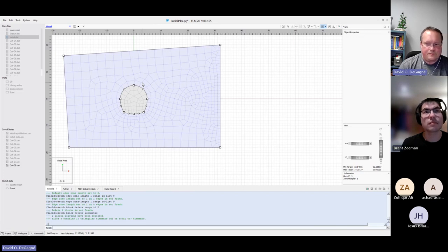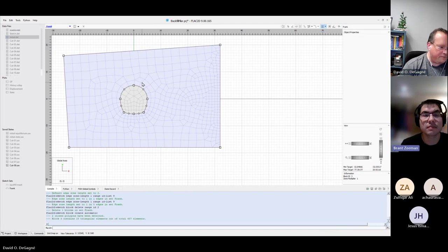And if we just delete it and it's high stress, you're going to start to see these artificial numerical effects. If it's low stress, not really a problem. But if it's high stress, the model can't really keep up like the Earth does. So anyhow, we call that zonking at ITASCA, or the command now is referred to as the relaxation or relax command, and it just lets you do that gradually.